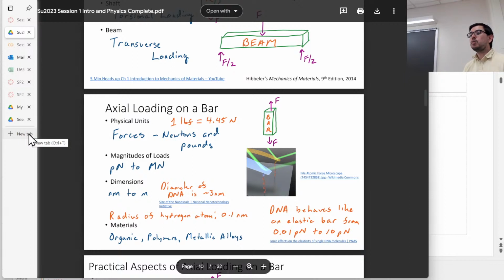What happens if you try to melt a thermoset? Well, it essentially chars. What's happening is you have all these spaghetti polymer chains that cross-link, so they form these bonds and they harden, and that's where it gets its elasticity, its rigidity. Okay, but the thermoplastics, they are essentially just being melted and cooled. Now there's crystallinity, there's other things that happen, right?